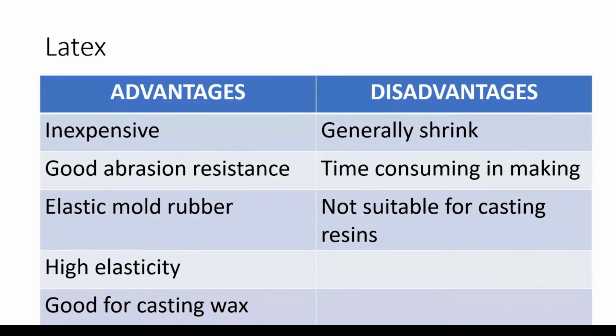For the advantages, latex is ready to use right out of the container, and latex is inexpensive. It exhibits good abrasion resistance and is an elastic mold rubber. Because of its high elasticity, a feature unique to latex is its ability to be removed from a model like a glove. Latex molds are also good for casting wax and gypsum.